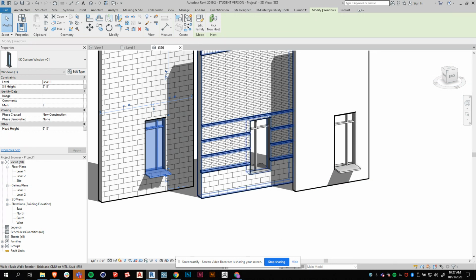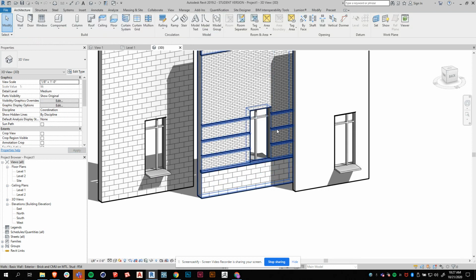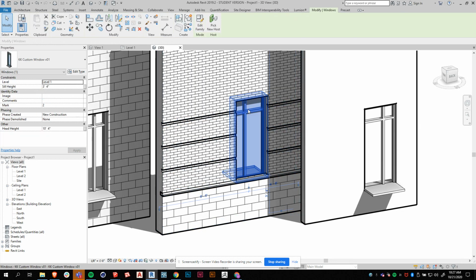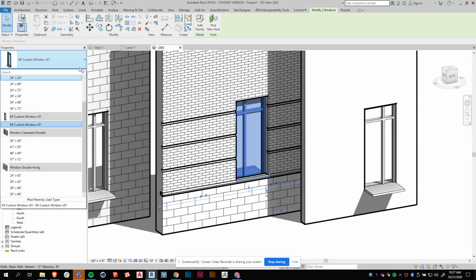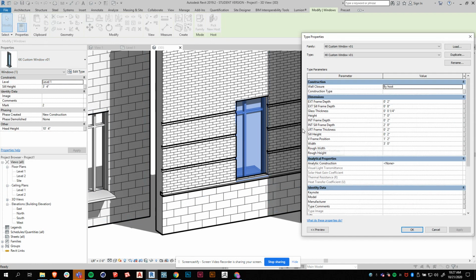So for example, if this was my exterior window system, I probably would want this window to end up sort of up here. So I might go on this particular window. Let's try 3 feet. It's probably 3'4". That's a masonry dimension, but you all knew that. That looks good, but now I might want to change the height of my window to not 7 foot, but 7'4". And now it's a nice masonry dimension, or I could have gone to 6'8".